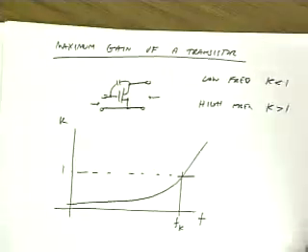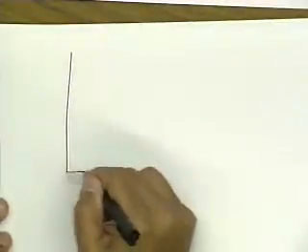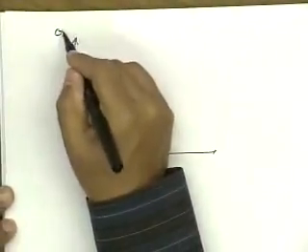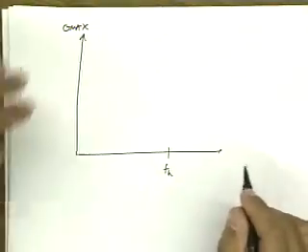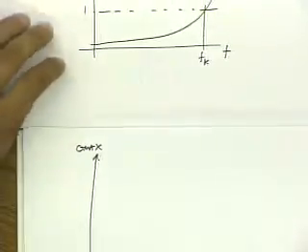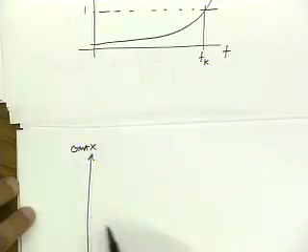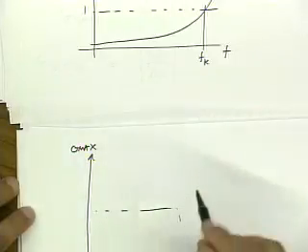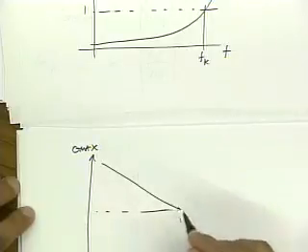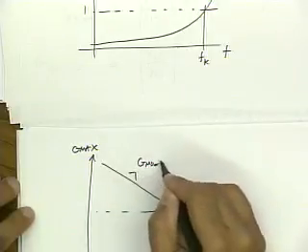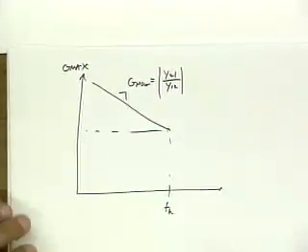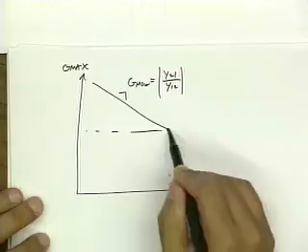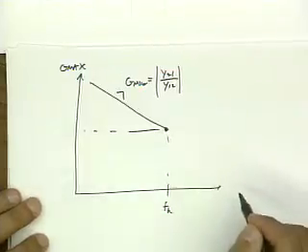So now if I plot the maximum stable gain I can get from my device, let's just call this G max, then up to the knee frequency, it's unstable, so I have to use the expression GMSG, which is just simply y21 over y12. Beyond this knee frequency, though, it's unconditionally stable.